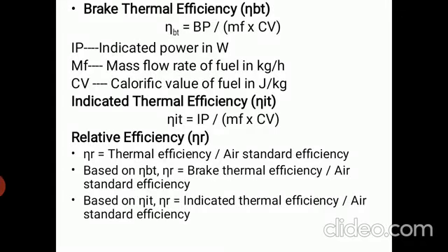Then brake thermal efficiency means brake power to heat supplied. Heat supplied is the mass of fuel, that is fuel consumption, into calorific value, that is the power supplied to the engine. Calorific value we have discussed in classes 10 to 12.